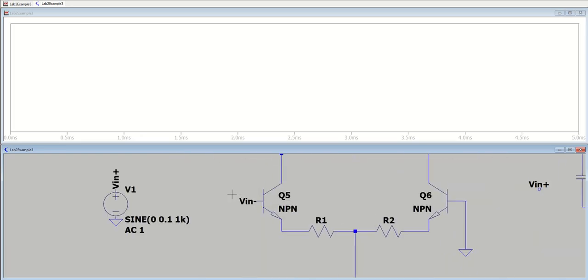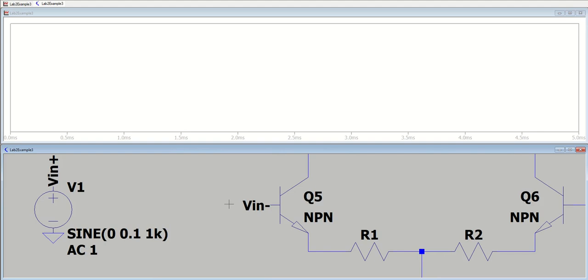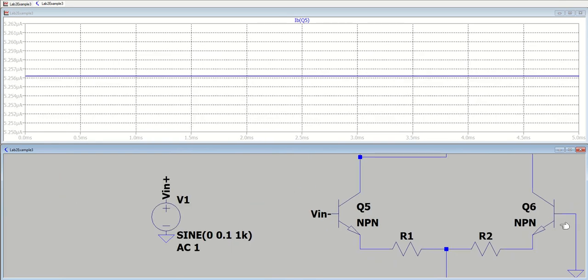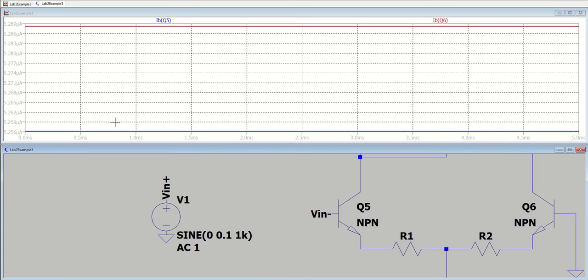and to measure current at the base, you just take your cursor, it's going to turn into a probe, and then get closer to the transistor's base and it'll turn into a circle. Once it's a circle, you can measure current. So do that for both sides. And now we have 5.289 microamps for the positive terminal and 5.256 microamps for the negative terminal.